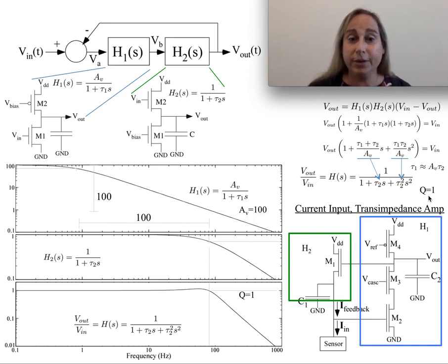And it's an interesting question how this plays out, because if I didn't do that, let's say I made the 2 taus equal, I don't get a Q equals 1, I get a much, much higher resonance in this circuit. And that may or may not be what I want, particularly if I'm making something that is going to have a robust step response. That's probably not what I'm looking for. And so what's the implication of that?